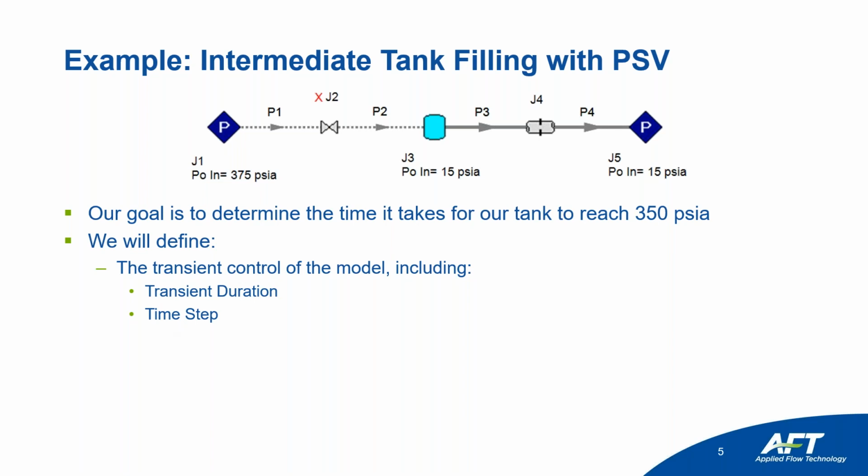So if we think about a 1-minute simulation, if we had a 10-second time step, that means we're running the first steady state for 10 seconds. We're letting whatever mass accumulate for those first 10 seconds. Then 10 seconds later, we're running a new steady state. That informs the next 10 seconds, the next 10 seconds after that, so on and so forth.